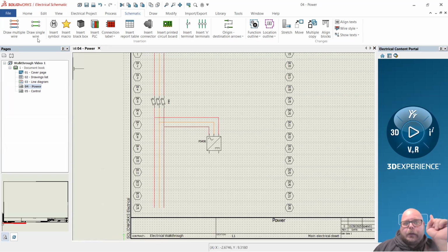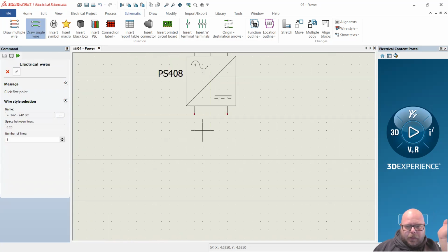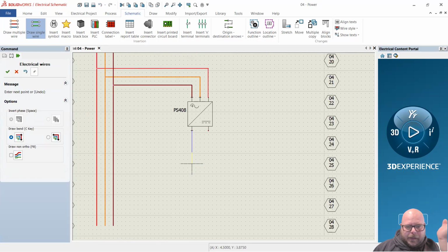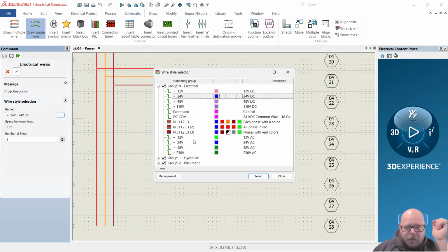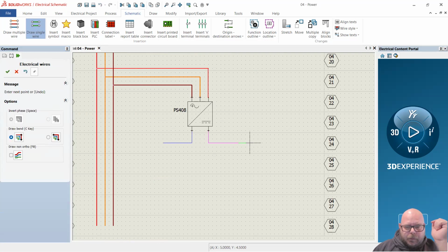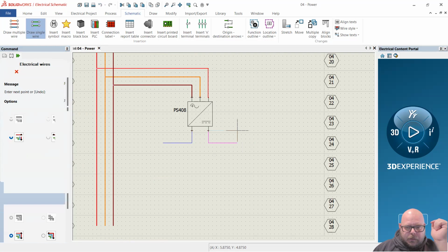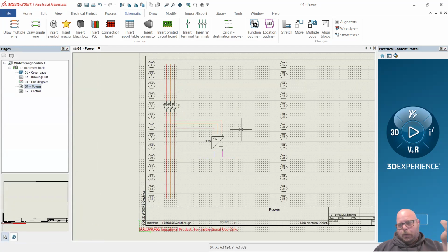This page is not done. I'm going to draw a wire, and now we need to get the DC out, right? I'm on a single wire. Let's call this the DC positive side, and I am intentionally going to splay it out this way. We'll get there in a second as to why I did that. And I'm going to switch now to my new common wire, DC common, and splay it out this way. Right. Now, as far as this demo is concerned, this page is finished.